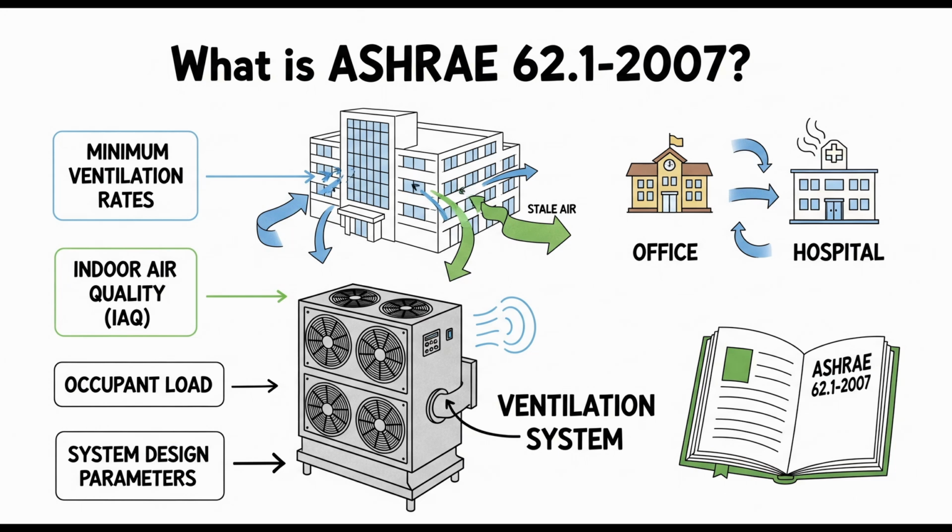Right. Little things matter, like don't run the ventilation systems without filters installed during construction. Why not? Because you'll just suck all that construction dust and debris deep into the ductwork and coils, and it's really hard to clean out later. It can become a source of problems down the road.